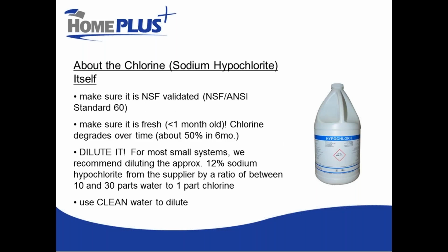Every time it injects, you have a very, very strongly chlorinated slug of water going through. It provides very, very poor mixing. You're far better to inject faster, but at a weaker solution, it'll achieve a much more even, steady, consistent result.